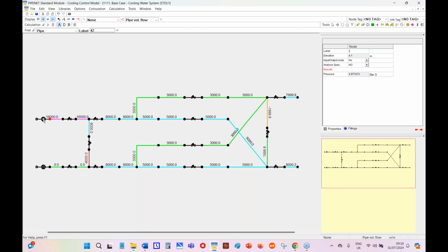What does it mean? It means that the control valves, for example, are less fully open. That's only 28% open and so on, because this pump is generating a pressure that's higher than the pressure we need. What is the consequence of that?